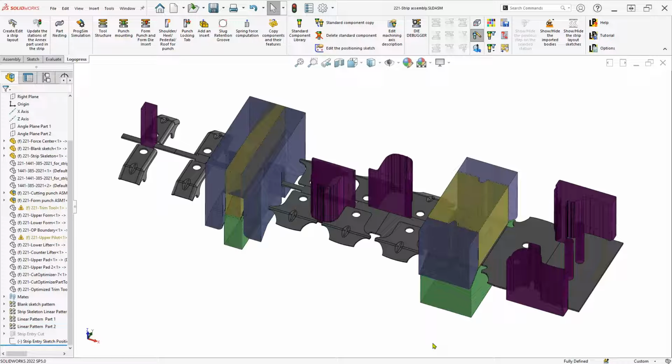Okay, thank you. So all the forms you showed were top down. I'm assuming you can do similar calculations running in a horizontal direction. Yeah, you can define cam motions coming in from the side. You basically just need to create a plane and say my motion is perpendicular to this, and then you can define how far, and the timing and the pressures and the various aspects on different angles.